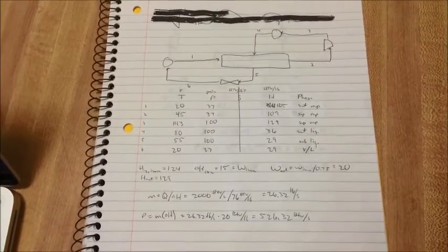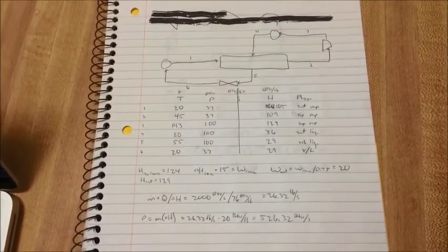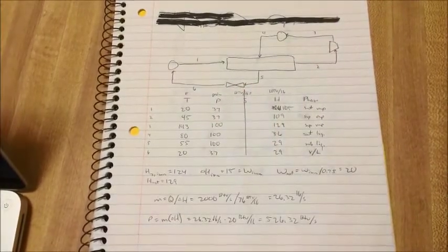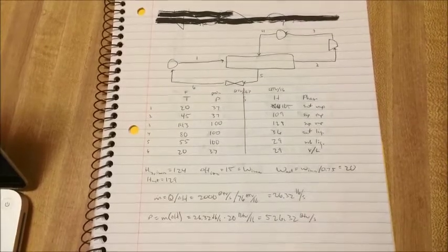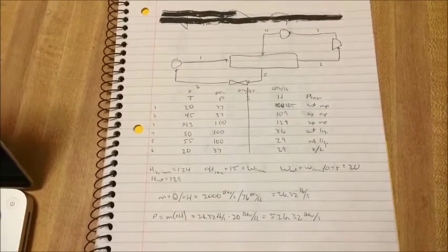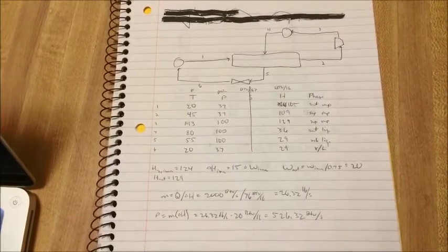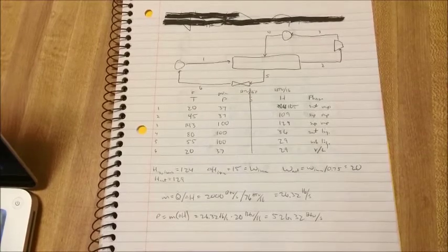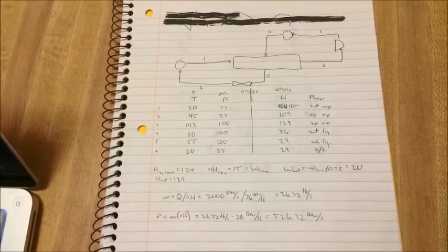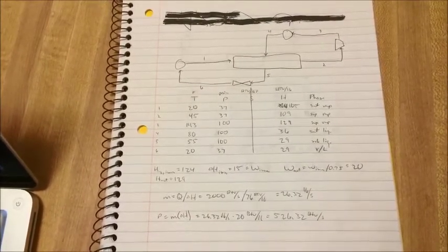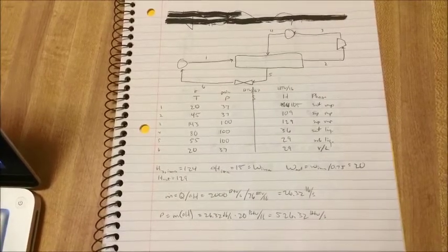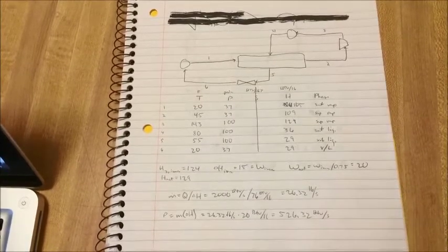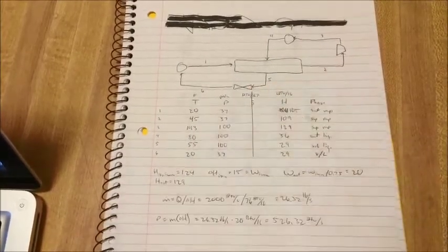Because we say that all heat exchangers operate at constant pressure, we also know the pressure of the two streams exiting the countercurrent heat exchanger because we know the pressure of the entering streams. We are making the assumption that the streams of the heat exchanger change temperature until they have a difference of 10 degrees Fahrenheit. So we also know that the temperatures of the exiting streams are 10 degrees different from each other, which are 45 degrees Fahrenheit and 55 degrees. We can now define all of the intensive variables of these streams as well.